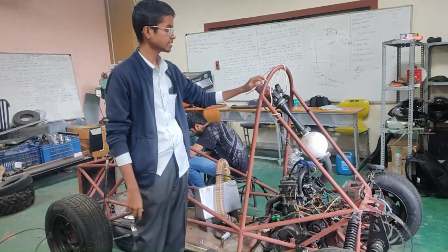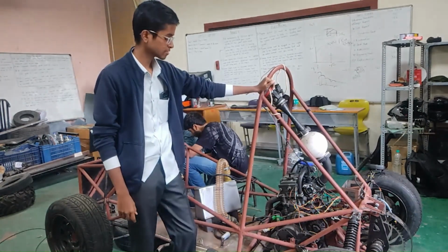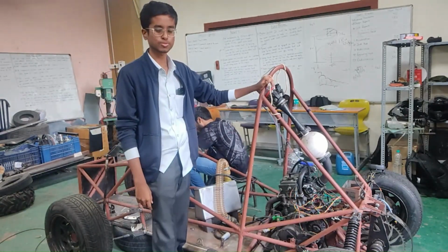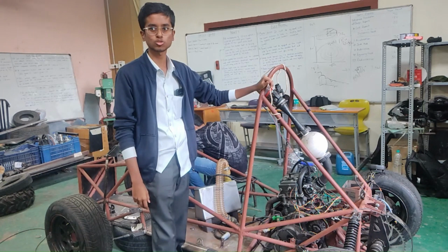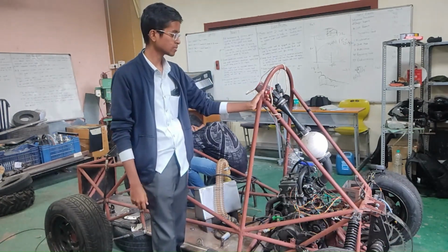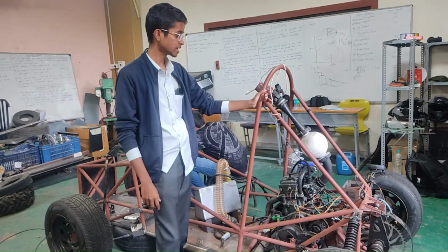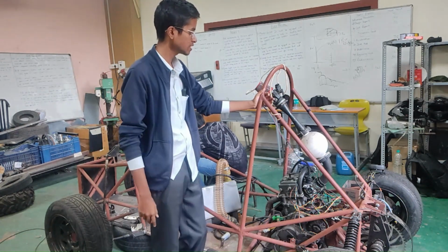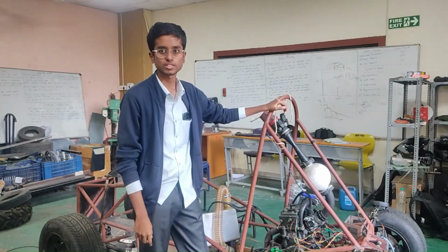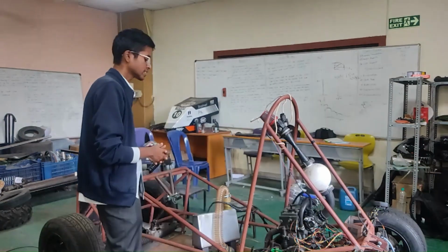If we compare with a regular monocoque chassis, where the body sheets bear the load of the whole car, in a space frame the whole frame withstands the total load of the car, and the body panels act as an aerodynamic shape, which provides better aerodynamic efficiency for the vehicle in high speed racing. Typically, these frames are not suggested for road going vehicles because they have fewer crumple zones and can damage